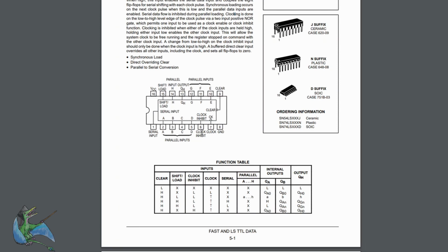Then there's a clock which is applied to it, and on every tick of the clock the device takes 1 bit and shoves it out of the output right here, and then everything plays musical chairs, it moves over. So it goes tick, tick, tick. With each tick, it will also read a new bit off of the serial input.